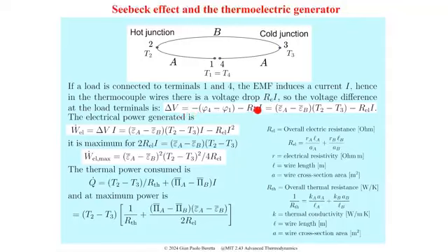So the voltage goes down. The more current you have, the lower the voltage. And you could actually go all the way to short. If you short the thing, you have the highest current, but it's all dissipated in Joule effect, in heating.